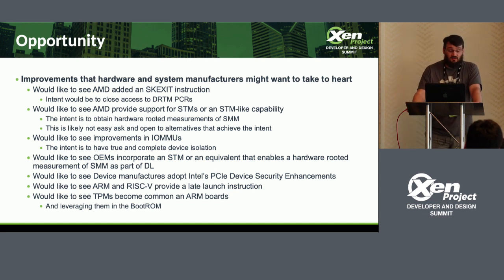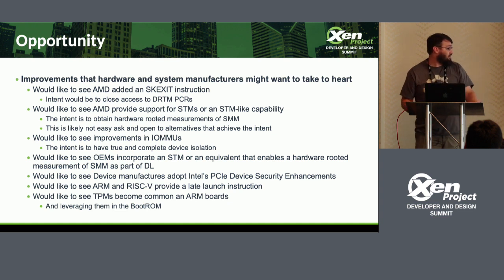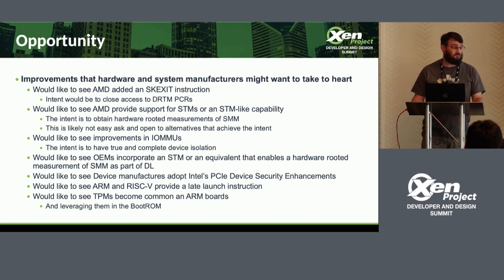TPMs, right? At the end of the day, you need a root of trust for all these measurements that you're taking. TPM is by far one of the best in terms of benefit versus cost. It's a very cheap little chip that you can put on pretty much any board that gives you a root of trust with fairly good strength of mechanism. I mean, it's not an anti-tamper device, but it still can give you a lot. And then, if ARM board manufacturers start incorporating TPMs, you just need to get it into the boot ROMs, so that you can have a measurement chain of ARM firmware.